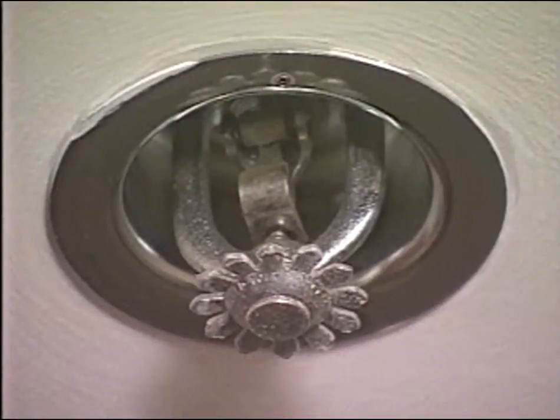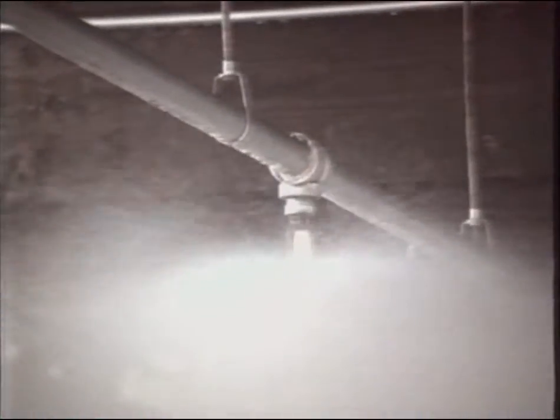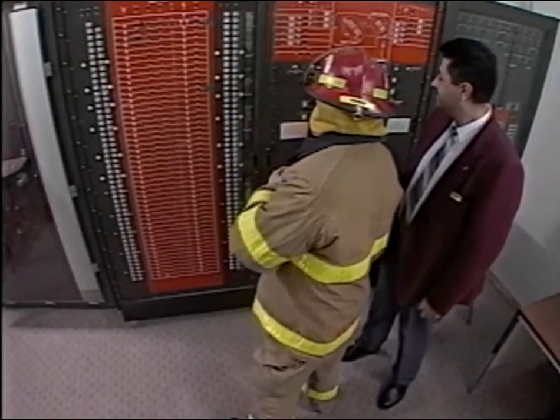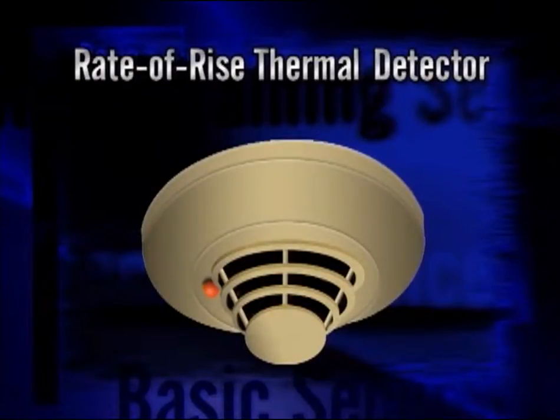In this system, a metal link is designed to melt when the temperature in an area reaches a certain level. When the link melts, it allows water to flow through the system, and a valve in the system detects the water flow and activates an alarm. Another type of fire detection is the rate of rise detection system. This system is activated when the air in an environment heats up at a rate that is beyond the limits of the system. In other words, the air heats up too quickly and the rapid heating triggers the system and an alarm.